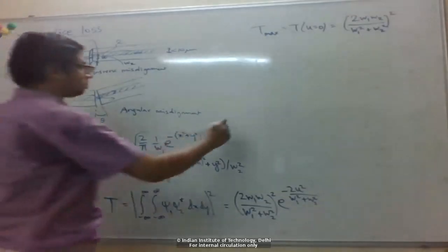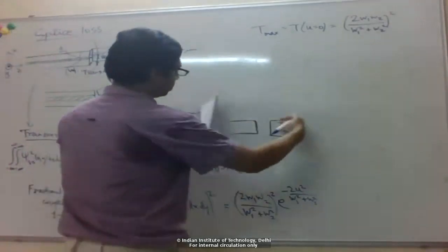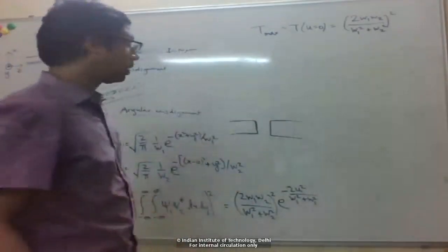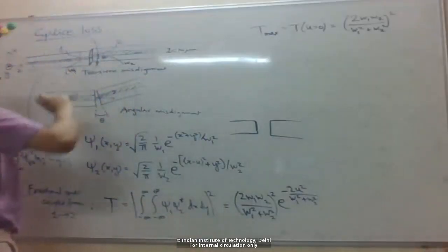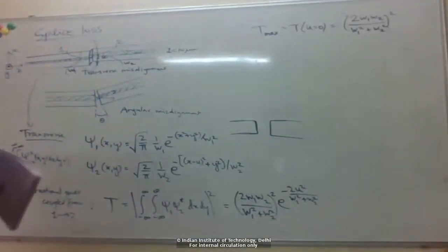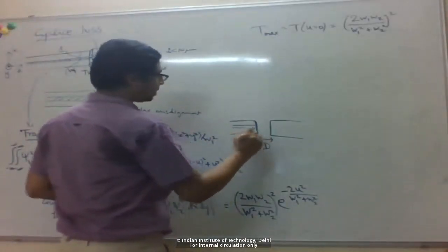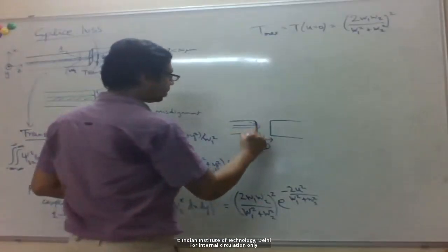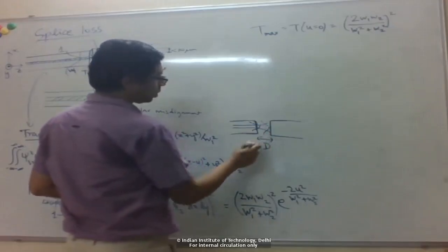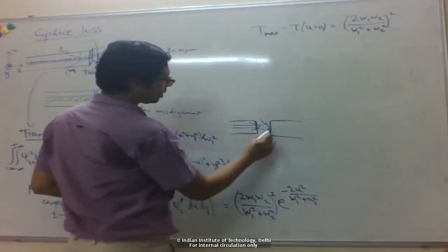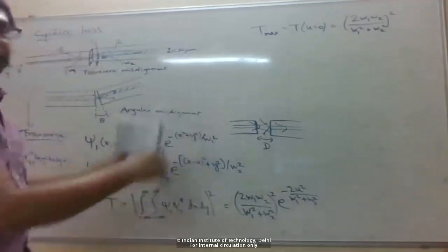But you could also take a gap if you want, right? But that is not a very practical case because usually the two ends are not left hanging like that. As I said, in the fusion splicer, when we splice, it's now a fused joint. But in the book there's a section which calculates this: you have some distance d here. The mode coming out here will diffract, so you need to take into account how much it diffracts out and then take the overlap with the mode in the other side. So you could calculate it.